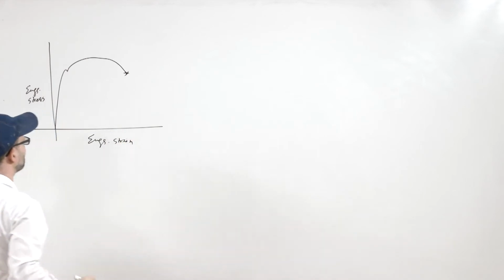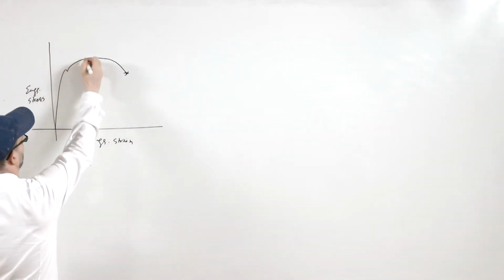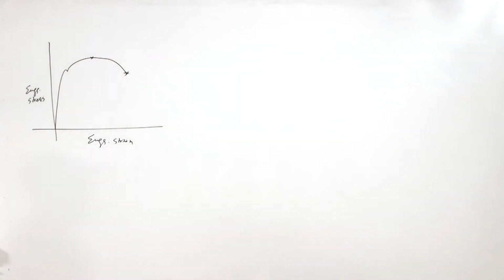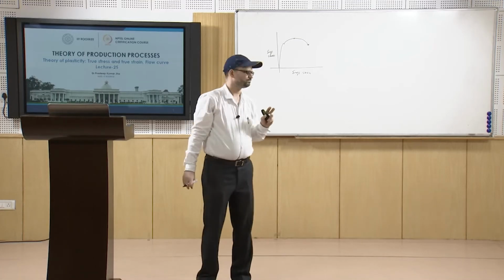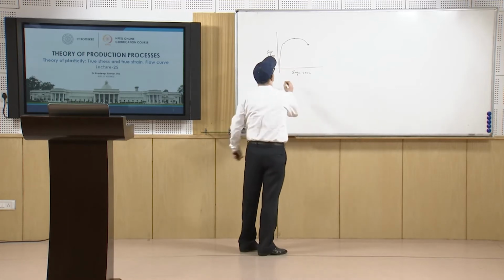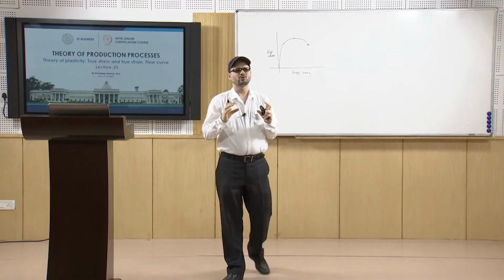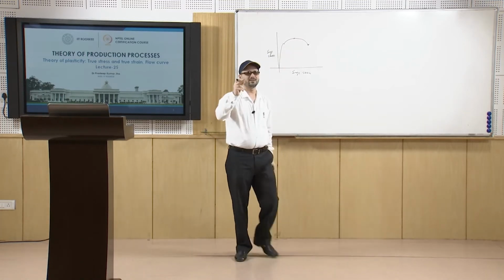Now in this case, what we see is that the stress is increasing, and then after that it will be reaching the maximum point, and then further it is decreasing. Now this curve basically is based on the original area of the specimen. So if you have the original area, some cross section is there, so always we find the stress based on the load divided by that area.